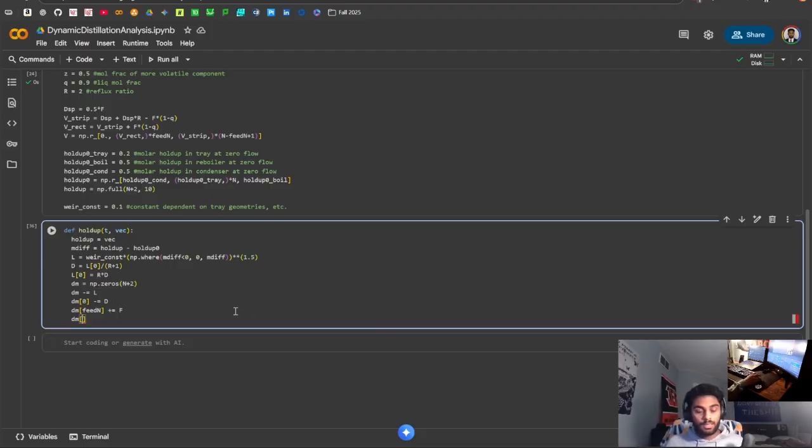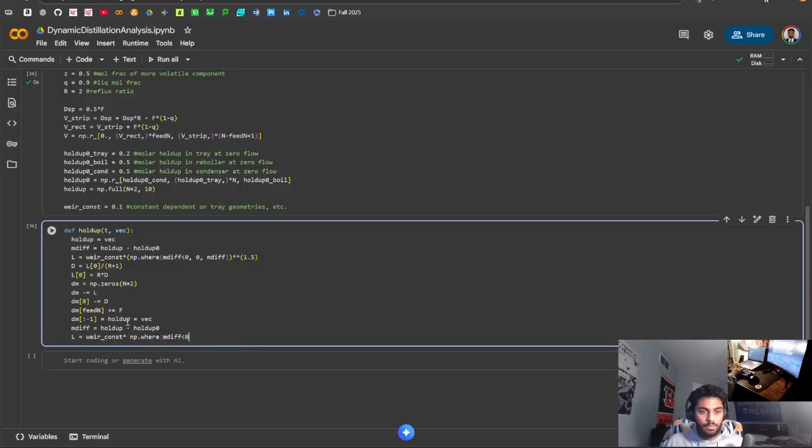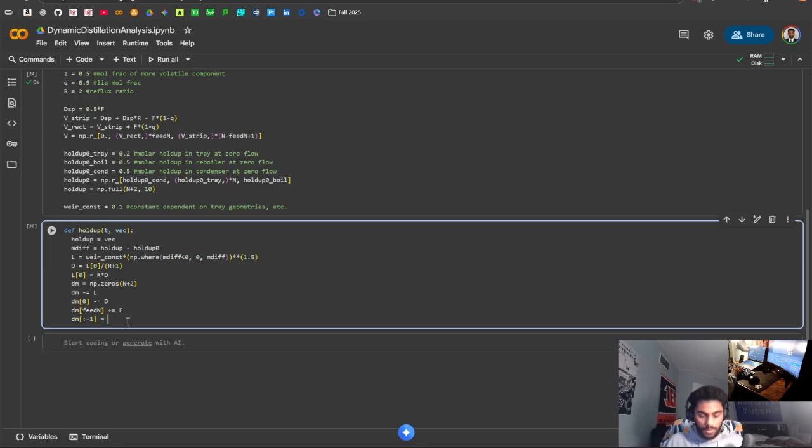We can do it in the sense that we include everything except the reboiler, which means we are looking at the vapor entering each system. We go to our vapor flow rates array and append by addition everything except that very first value for the condenser, because no vapor exits the condenser.